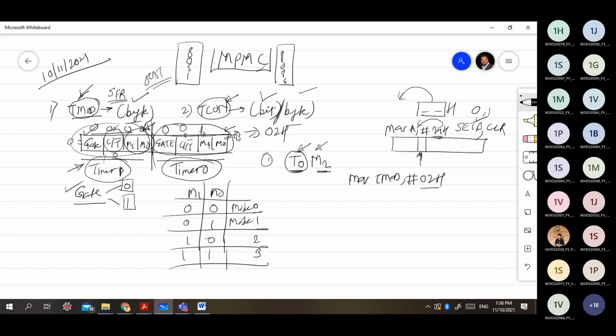Okay. Now, what do you mean by byte addressable? Just like this, I want to use Timer 0 in a mode. To do that, we have to put all the fields as zeros and ones appropriately, get that 8-bit value, and then place it into TMOD. That is what is called byte addressable. But if you observe, we actually need to change only one bit, that is M1. Only this bit we have to make 1 and the rest of the bits will be 0.